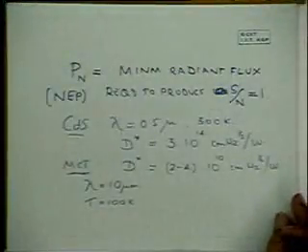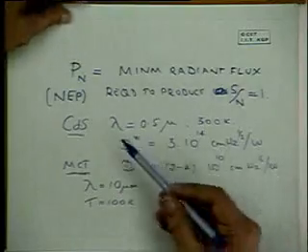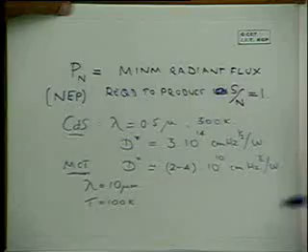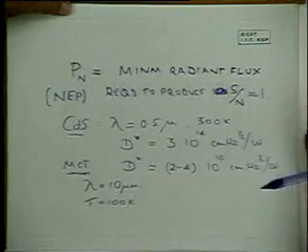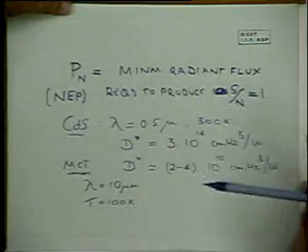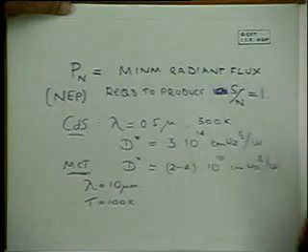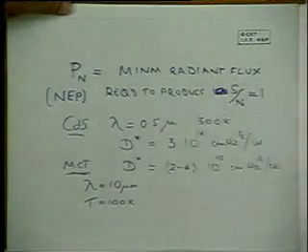For example, if you have a polycrystalline material, it is material dependent. You have grain boundaries, and conduction between grains can give rise to noise. If you have single crystal material, no grain boundaries, there is no noise due to carrier fluctuations.